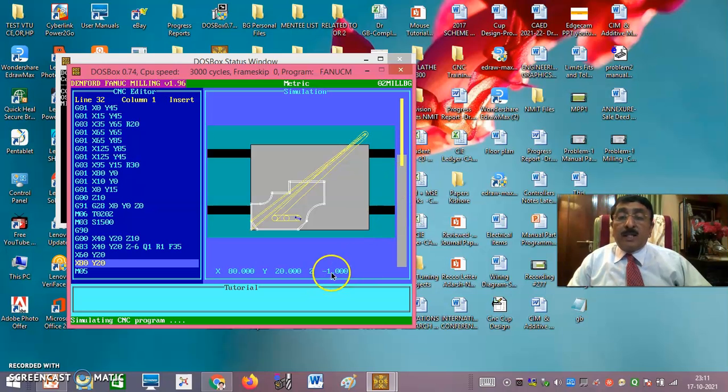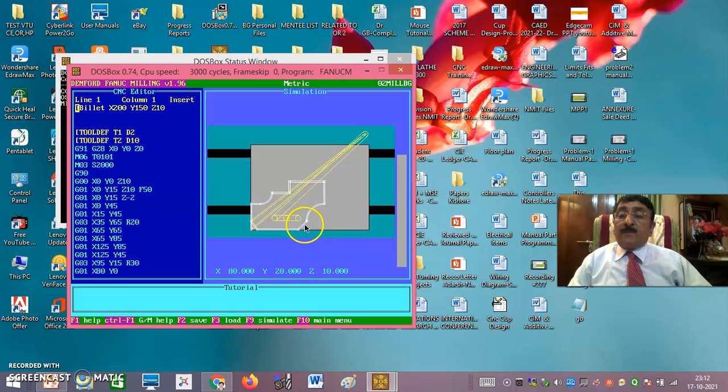This is -1, -2, -3. Going above 1 mm. -4 it will become. Going above by 1 mm. -5. Going above by 1 mm. And then -6. Okay, by doing this, the chips that have collected in the hole will be removed.